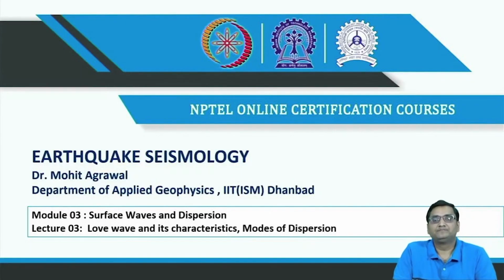Hello everyone, welcome to lecture 3 of module 3. In the previous lectures of module 3, we discussed the basics of surface waves. Then we discussed the equation for the Rayleigh wave, and we also discussed the equation for the Love wave. In today's lecture, we will be discussing Love waves and their characteristics, and most importantly, the various modes of dispersion.